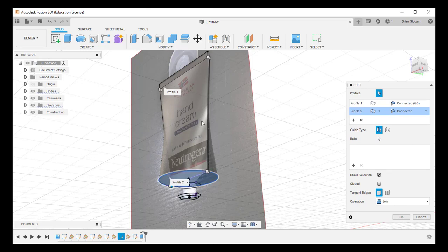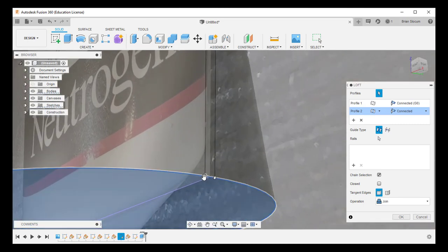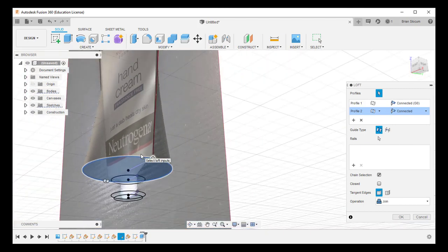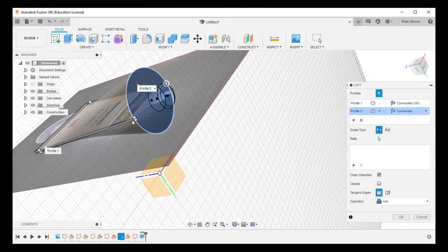That's the cool one, because it's making the round go into that flat rectangle. The only weird thing about this is it's starting with these 2 points here, and so I'm going to adjust these so that these 2 points fall on that center point, so that my tube is completely round at the bottom. And I'm going to do the same thing over here.